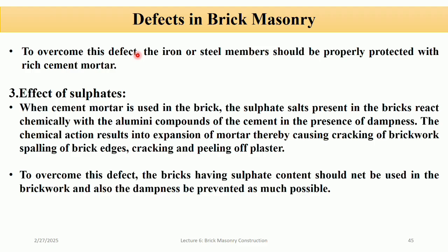In the case of steels, chlorides from de-icing salts, seawaters, or contaminated cores can accelerate corrosion. Carbon dioxide in the air reacts with concrete, reducing its alkalinity and making embedded steels vulnerable to rust. So the effect of steel corrosion is loss of structural strength and durability, expansion of rust leading to cracking and spalling in reinforced concrete, increased maintenance cost, reduced lifespan of the structures, and potential failure of the metal connections and fasteners.